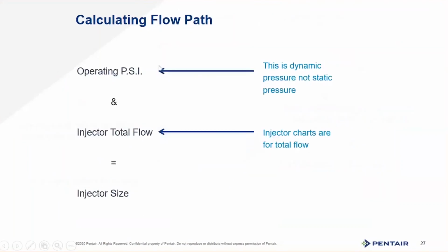And this is operating PSI, not static PSI. That means when we're flowing water, what's the pressure going in? I'm a big fan of pressure gauges before and after systems, so I can understand what's going on. Seldom done in residential cases. Maybe it's done when you're checking things out and setting things up, but normally pressure gauges don't exist in homes. Businesses, good idea to put these in before and after. Great for troubleshooting. Injector charts are for total flow. You're going to get that from us in our manuals for the valve. Equals injector size.